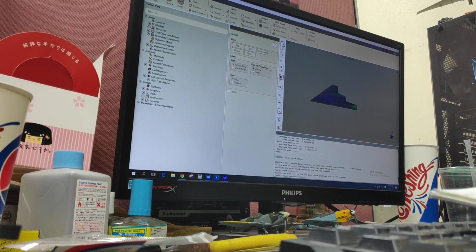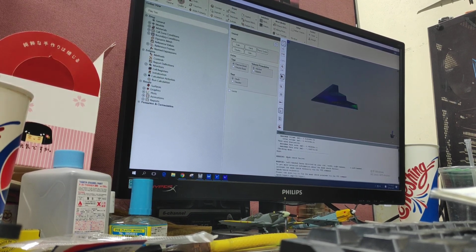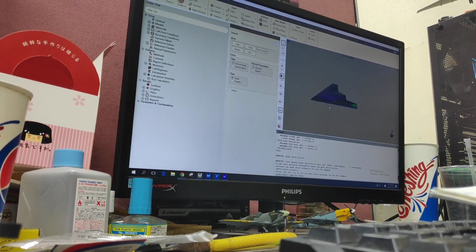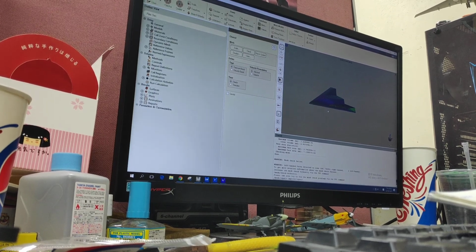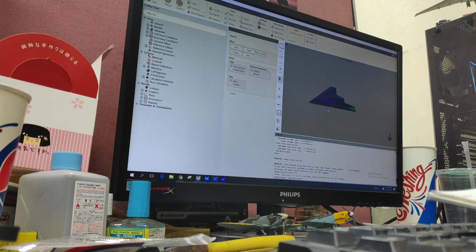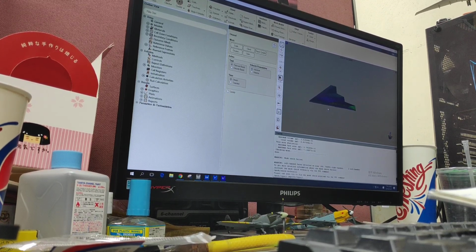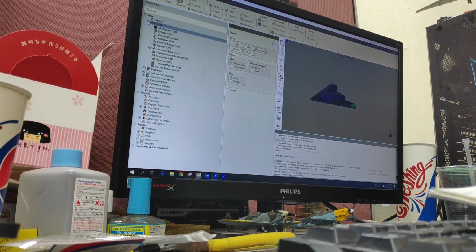Okay. You can find there's a warning says mesh check fail. It's normal because we are using the polyhedral or poly-hexcore mesh. Okay, it's normal. They will show the mesh check fail. Okay, now we go into the models because we have all checked.